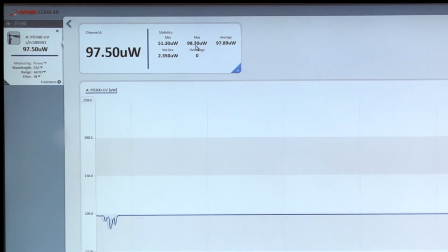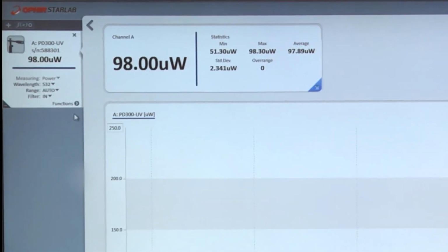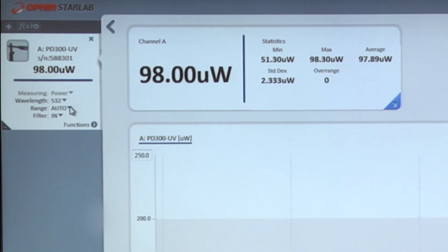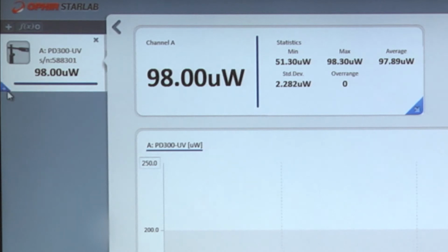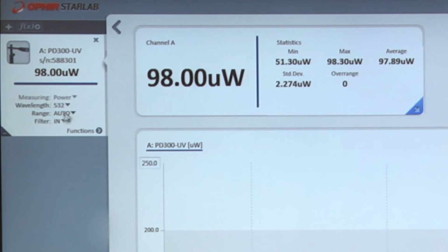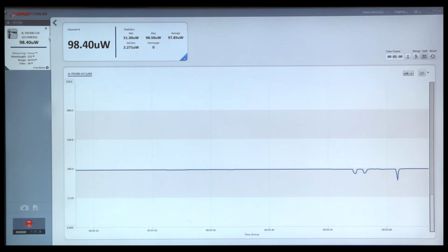The particular configuration of parameters that need to be set and units that need to be set vary from sensor type to sensor type. For example, if we were using a pyroelectric energy sensor, we would also be prompted to set the maximum pulse width, the threshold energy level, and so on. There are a number of advanced functions that we'll briefly look at.